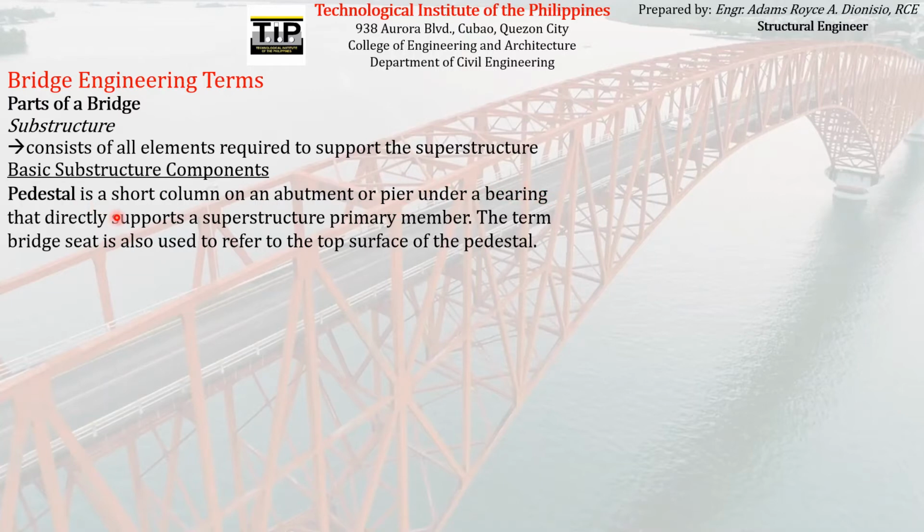The purpose of the pedestal, just like the bearing, is to distribute the loads that are being transferred from the superstructure to the substructure. So that's one purpose of the pedestal, to evenly distribute the load transfer, so that there will be less stress produced on the interface of the substructure and the superstructure.